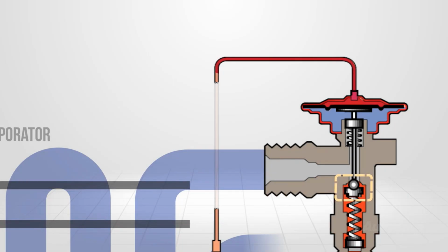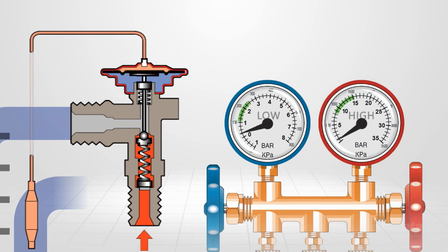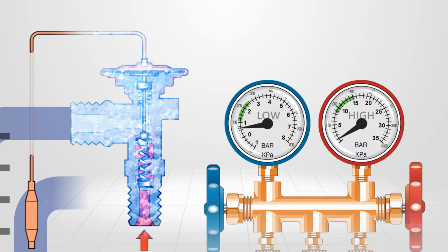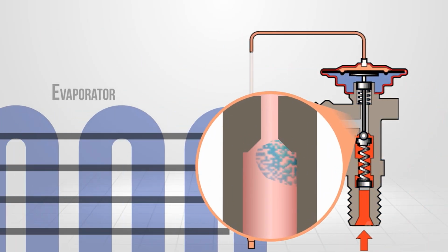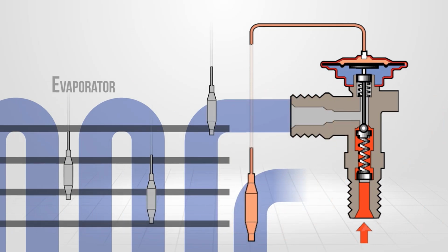If the expansion valve is stuck closed, there will be insufficient refrigerant flow through the evaporator and suction side of the system. The corresponding pressure gauge readings will be significantly lower than normal. This may be accompanied by frosting of the TX valve. The sticking valve may be caused by moisture entry causing rust formations, or an incorrectly positioned or faulty evaporator thermistor.